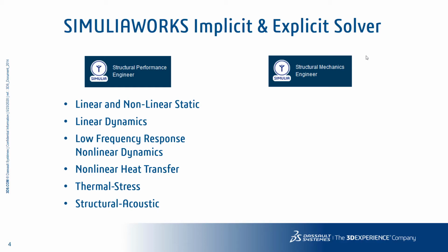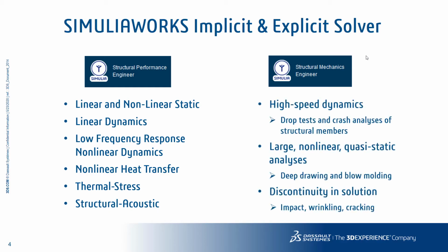With structural mechanics engineer, you will get everything that comes as part of structural performance engineer, and with the addition of the explicit solver, you'll be able to do high-speed dynamics, so any type of drop test or crash analyses, and large nonlinear quasi-static analysis, so you'll be able to simulate deep drawing and blow molding. And any problems or solutions that have discontinuities, such as impact, wrinkling, and cracking, would need to be solved using an explicit solver.